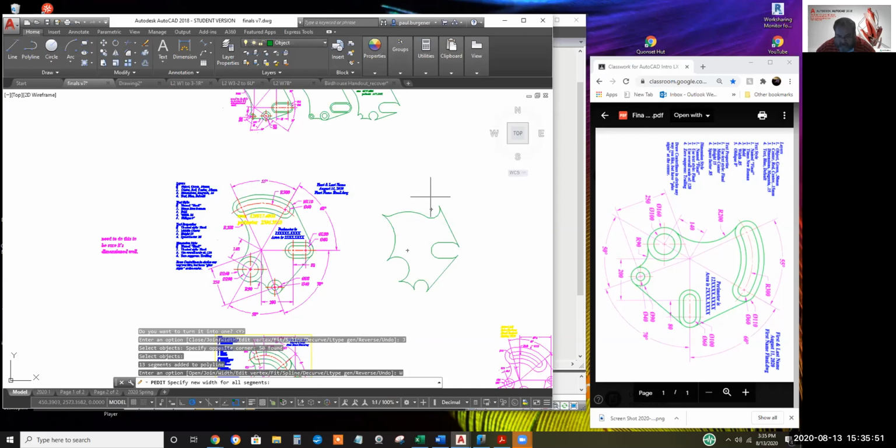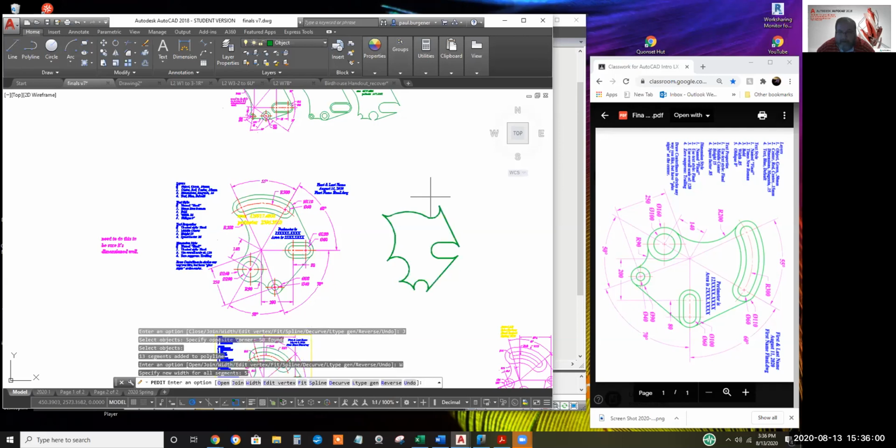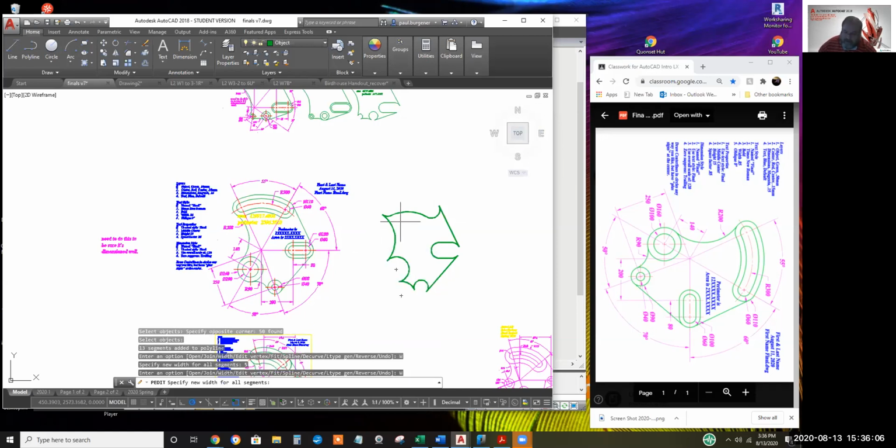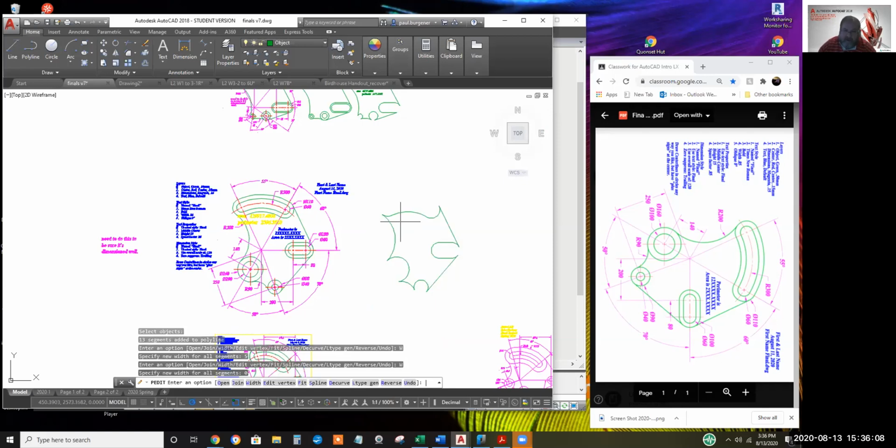Maybe you say a width factor. I'll swell out all the polyline widths so that they're all 5 units wide. There you can see it all swelled up. I can undo, or invoke the width option back again just to keep things razor sharp with a 0 width.